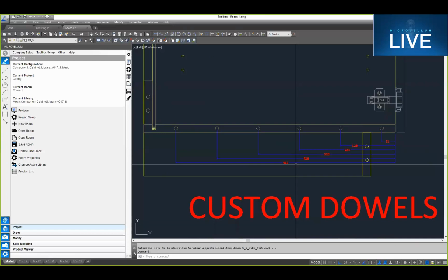But if that's not something that you're looking to do, you don't want to include those barcodes, and you just want to use standard programs out on your CNC horizontal boring machine, then you could have, if a part is from X to Y size, it's this program, and the operator then opens up that particular program to run those parts. And if it's a deeper part, then he uses a different program. You certainly have the control to be able to do that.